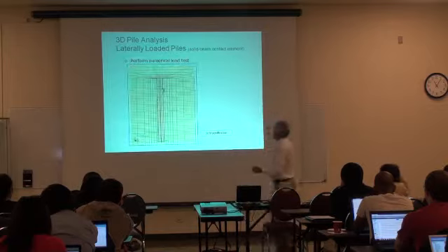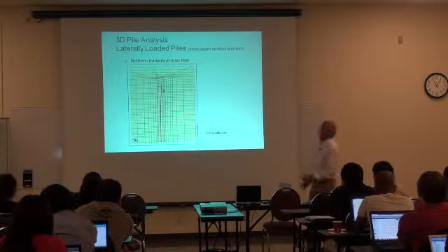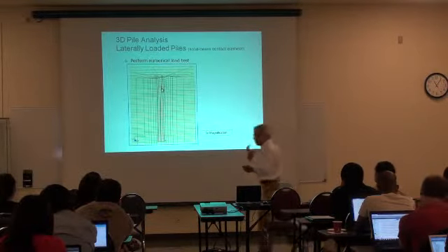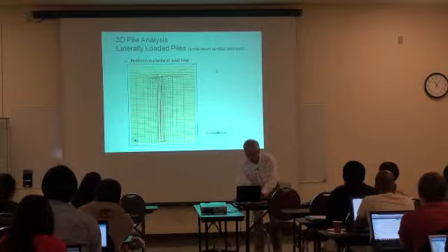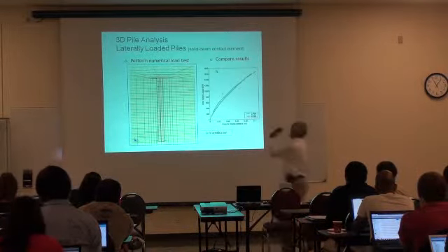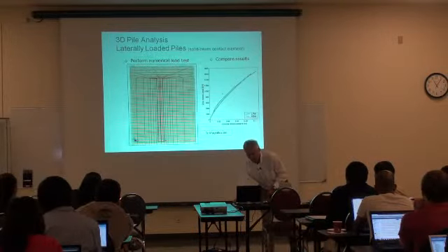So let me see if it does it. You see, as I push, look how the soil is pushed in the lateral direction and also in the upward direction. That shows that the element is working well. We validated this using, again, LPile and other tools to see that we were getting the appropriate displacements, etc.